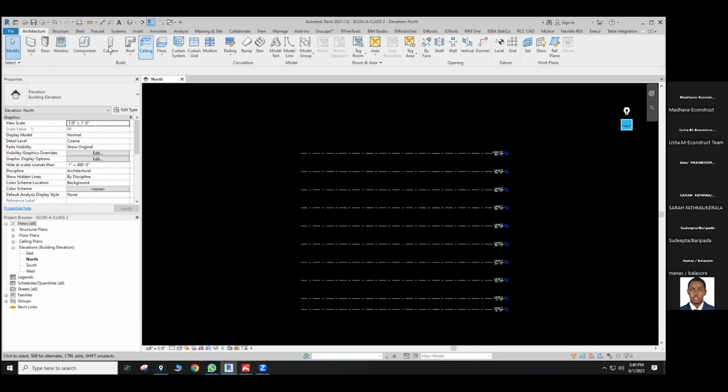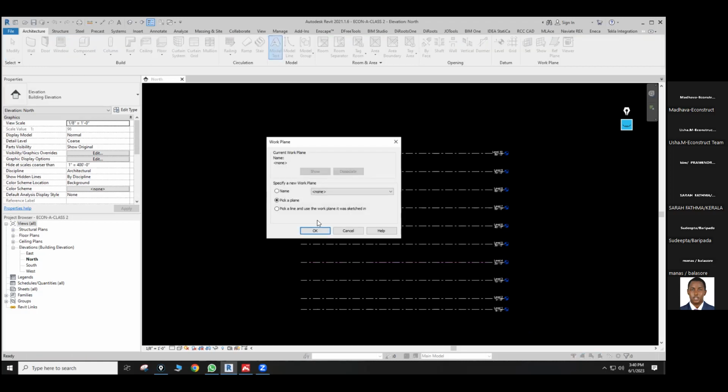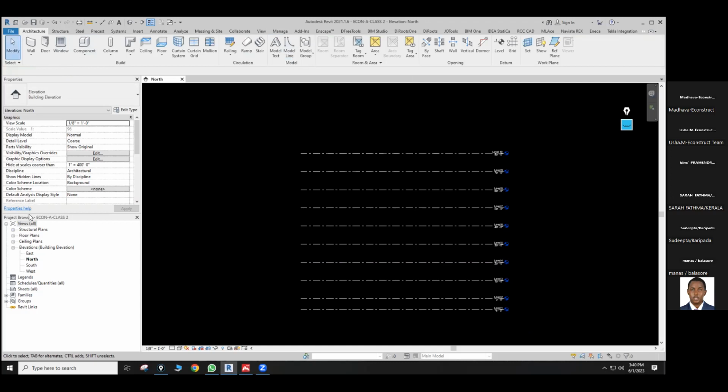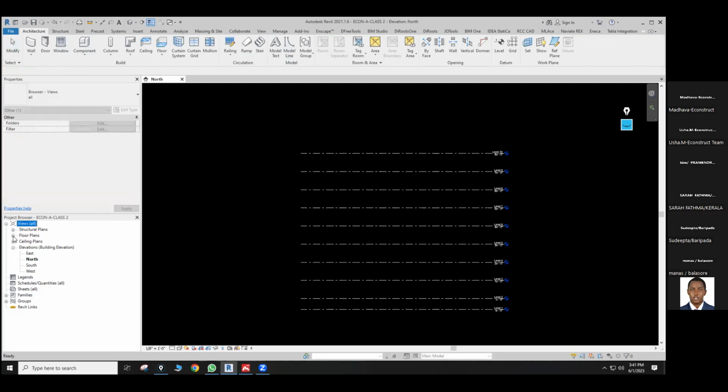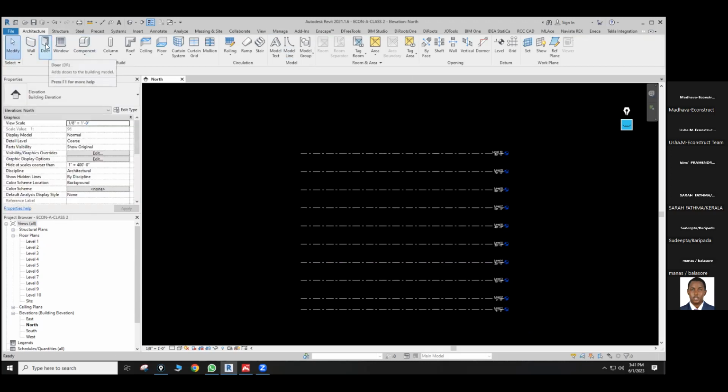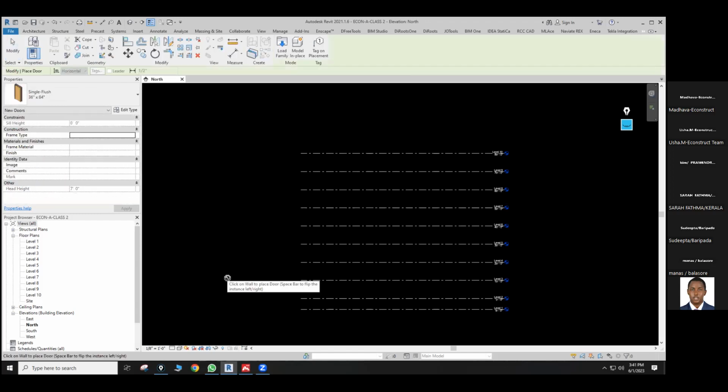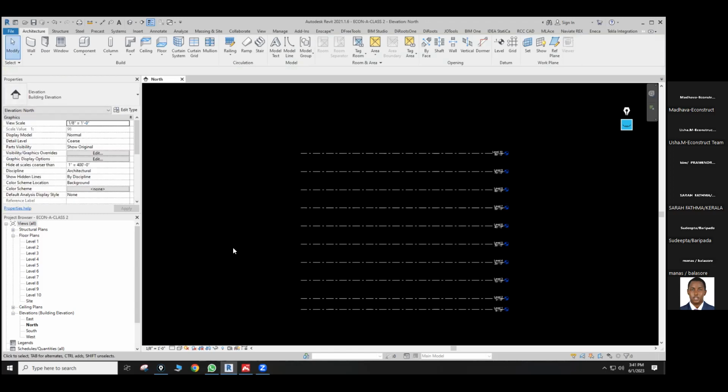So once you take any kind of command, for example, if I need to place a text, or a model, or create a model line, or a dimension, the command is activated. Therefore, what we need to do is escape. If I take one command here, like architecture wall, my command is activated here. See that. Once I escape, my direction has changed.